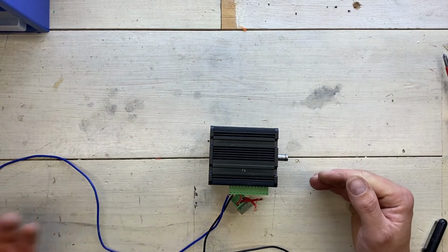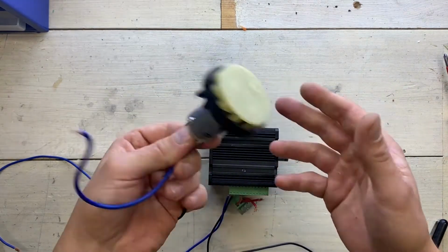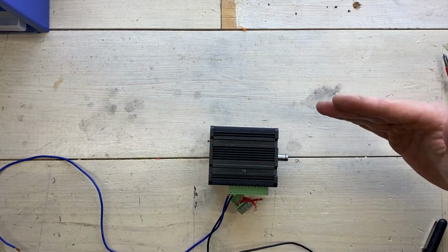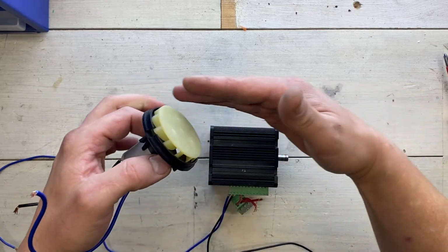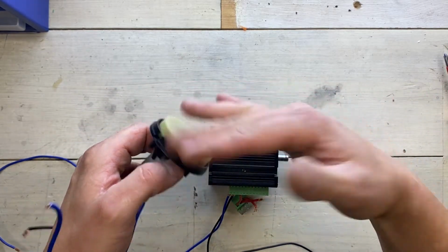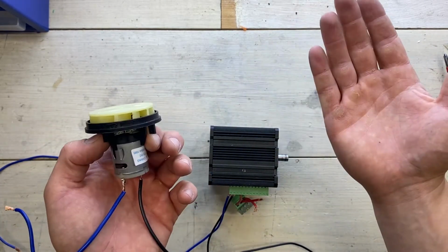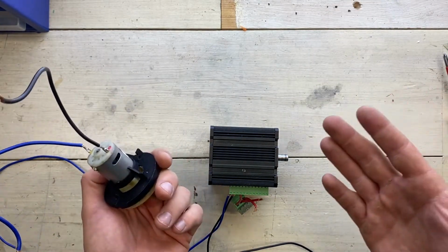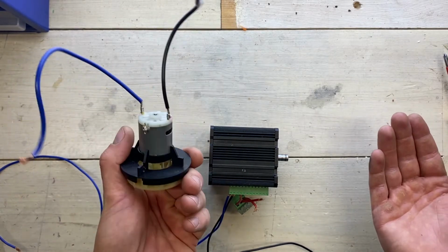Then you had a DC motor, actually not too dissimilar from this one, and then you measured the position of the axes. And when the position of the axes were where you wanted it, you turned off the motor. Simple as that. And if you find any really old school CNC machines from the 70s or early 80s, this is probably how they worked.